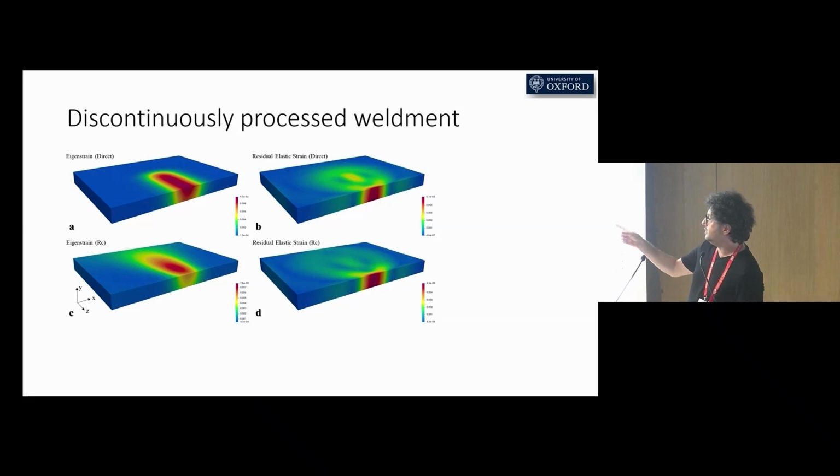Of course, first we determined the distribution of eigenstrains, and then quantified residual elastic strains. After reconstruction, we remapped 3 components of eigenstrains and 6 components of residual stresses, and here I show you their magnitudes. And yes, this experimentation showed that we can get very good reconstruction in the whole volume using data only from the front face.